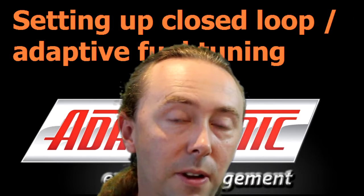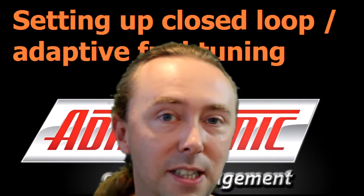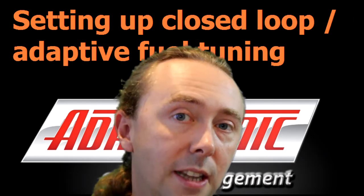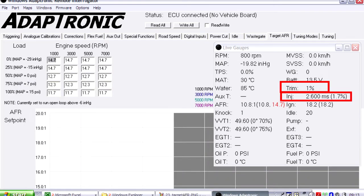Closed loop fuel control mode, or what a lot of people just call closed loop. We don't just call it closed loop, of course, lots of other things are closed loop as well, such as variable valve timing and idle control and that sort of thing. But closed loop fuel control is where the ECU has a target air-fuel ratio that it's trying to achieve, and it compares the value that it reads from the sensor to the target and then adjusts the injector milliseconds using a trim percentage, which is applied to try and get to the target air-fuel ratio.